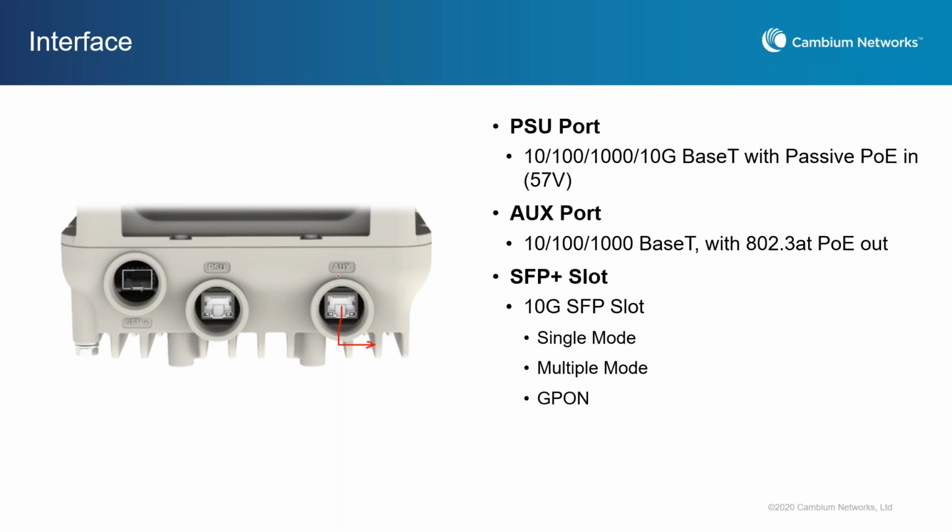Thanks, Alan. The next question is, are CN Wave products planning to use a 1 gig channel instead of a 2 gig channel, or do they have it in the roadmap? Okay, so currently we're using a 2.16 gigahertz channel, and when we do channel bonding, we're going to support a 4.32 gigahertz channel. We have no plan to support the narrower 1.08 gigahertz channel.